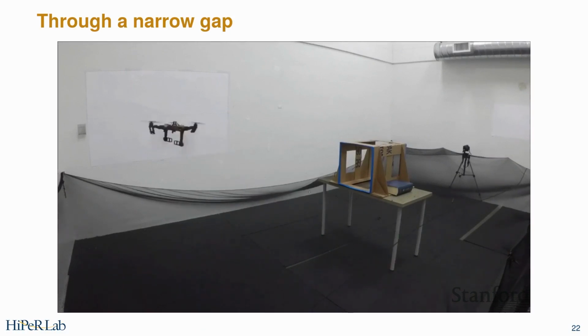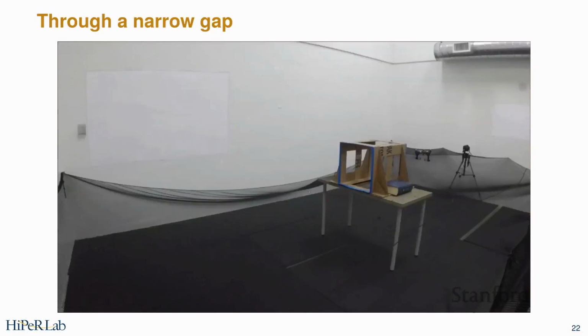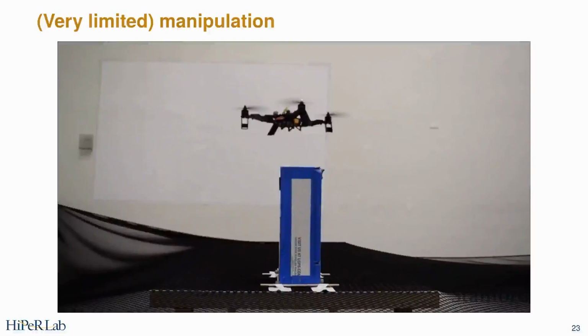On the one hand, obviously, just because the disk area is much smaller, so half the size, so that's going to be a much higher power configuration. But also the yaw torque you need is actually quite high, and the propellers are very inefficient in reverse. But you can do things like do these flights. You can also do other things, like some very limited manipulation.